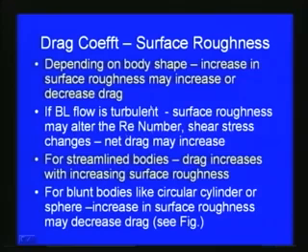Then another important parameter as far as drag force and coefficient of drag is concerned is the surface roughness. For the same body, if it is smooth, then the coefficient of drag or the drag force will be different, and if it is rough, the coefficient of drag will be different. Depending on body shape, the increase in surface roughness may increase or decrease the drag. So, this depends upon the shape of the body also.